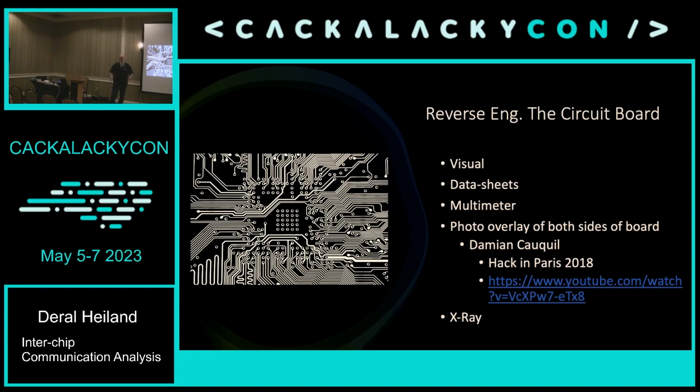Is it a two-layer board? Is it a multi-layer board? How do we deal with that? A gentleman named Damien Cauquil out of Paris did a great presentation at Hack in Paris where he talked about photo overlay of the board to actually map out multiple layers through the vias, through the circuit board as part of this process. And it was a real good discussion on that particular topic.